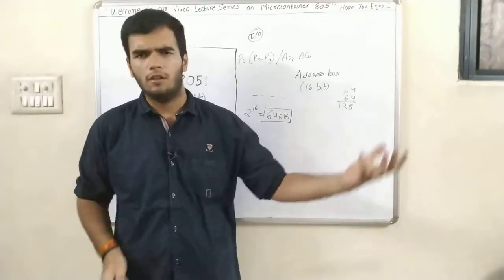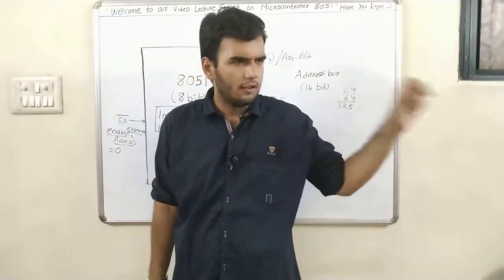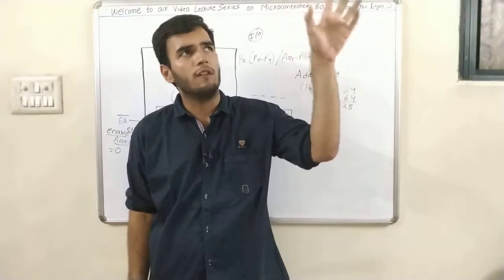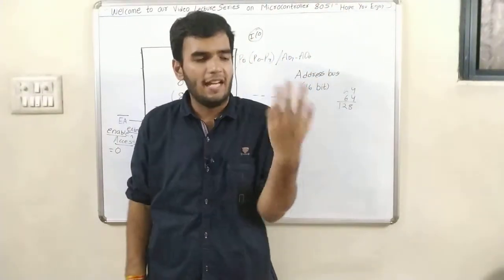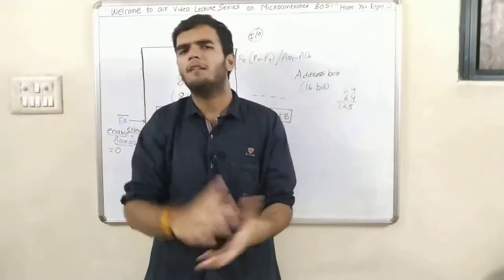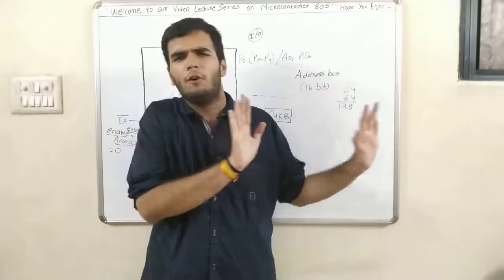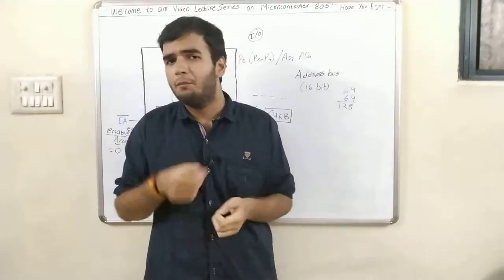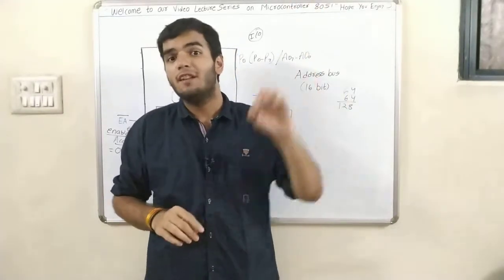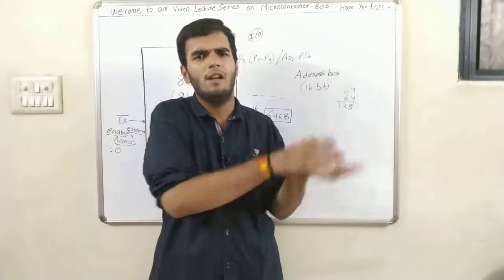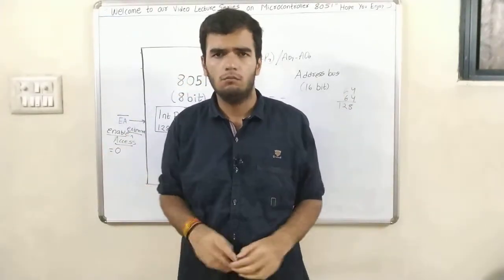Let us just recap. Out of 40 pins there are 32 pins for ports. Port 0 has 8 pins used as a multiplexer. Address bus plus data bus is called multiplexed. Further, 8 pins for port 1 are simply for taking input and giving output. In port 2, the remaining 8 bits of the 16-bit address bus are used. Port 3 has 8 pins separated into groups.